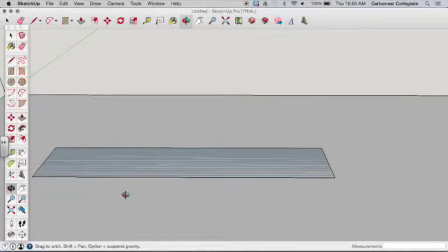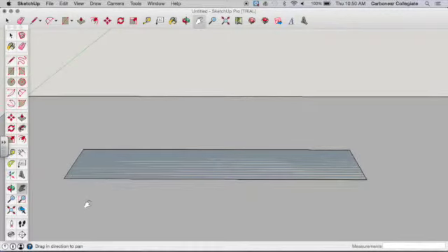Next thing we have to do now, that's a good time to use the dimensions feature, is identify the dimensions of our project. So to do this, we select dimensions from the toolbar, and in order to show dimensions on any given side, you simply hover over the line till it turns blue, click the line, and move your mouse away from the line.